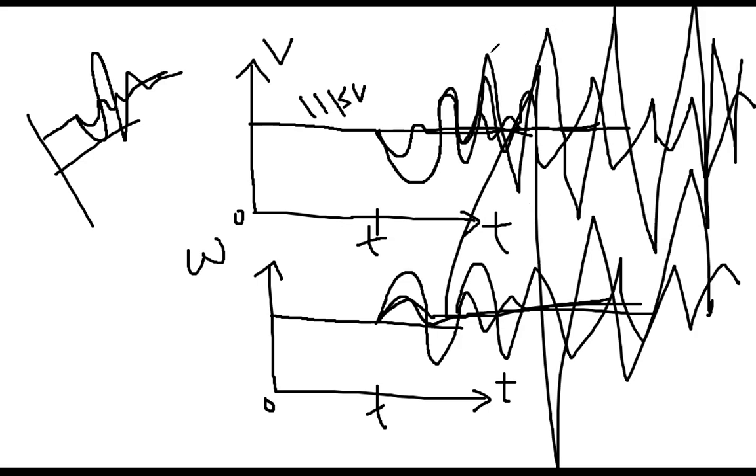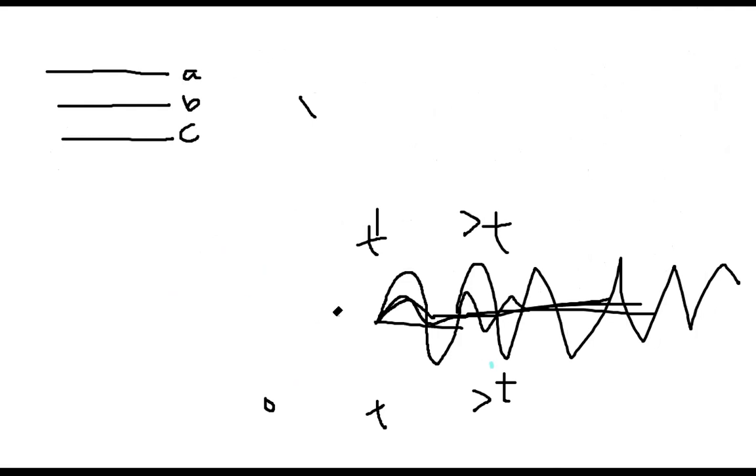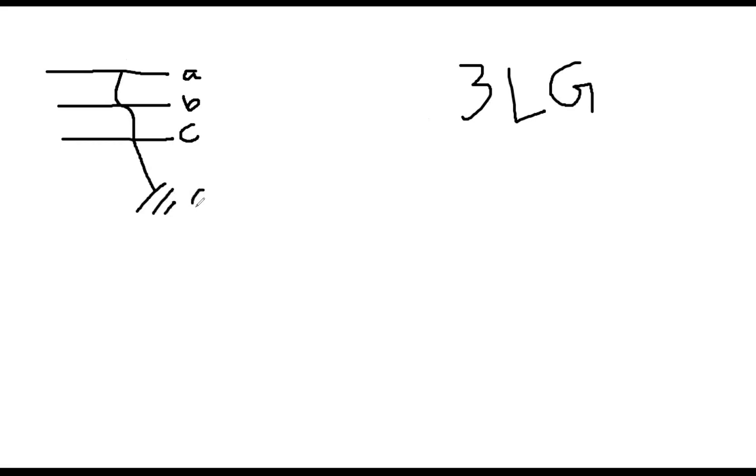And I think I was mentioning various types of faults. So let me just clean this portion. Now look at this one. For example, we have 3 lines, AH, BH, CH. In the previous slide, those are written. For example, the type of the fault is 3LG. What does that mean? 3LG means it is shorting all 3 phases, and then it is grounded. This is the grounding, the land or soil.